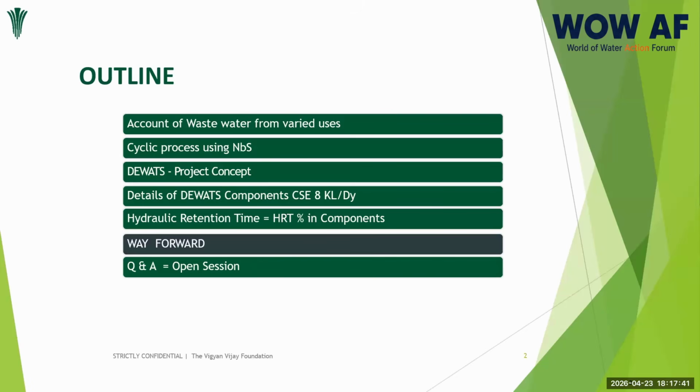In certain spaces we would like to be very, very cautious. For example, laboratories and other clinical areas where the water is coming out, we don't like to lead it directly into this DEWATS plant. We would like to pre-treat it and then send only the water. So this process is tabulated, and I'll be explaining the DEWATS project concept. Then I'll be explaining the various DEWATS components.